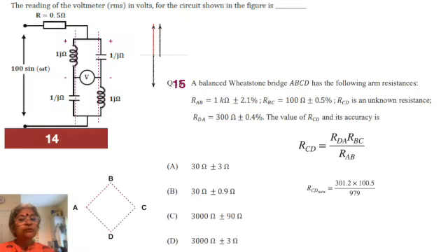It looks like a Wheatstone bridge. It is not. Let's see why. Because the left hand side gives you j by 1 by j, which is equal to minus j squared, that is minus 1, on the numerator. On the right hand side there is 1 by j by j, which is equal to 1 by j squared on the denominator, so it's going to be minus 1 on the denominator, which is mathematically equal but electrically not. So be careful.